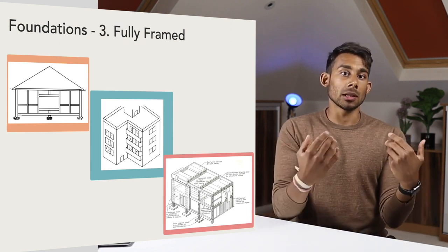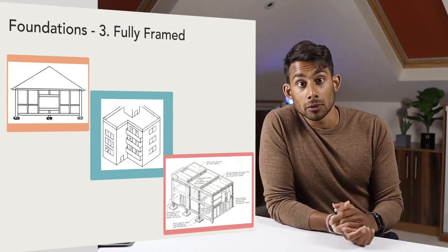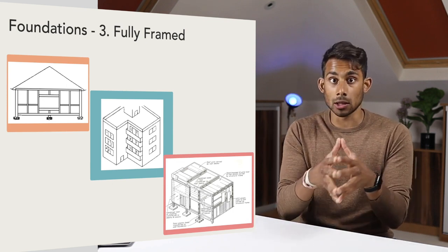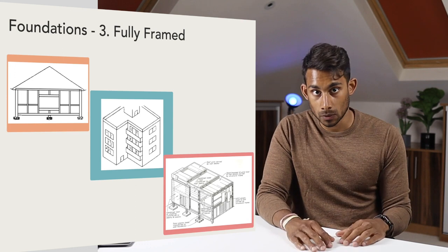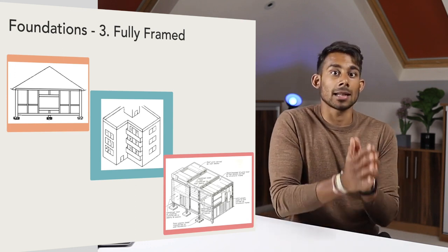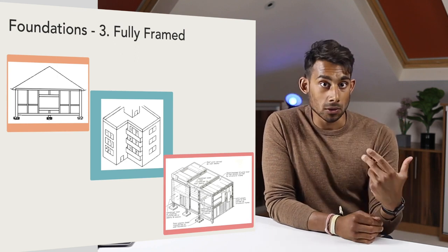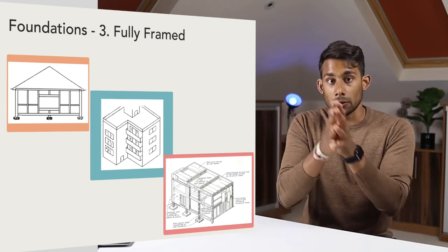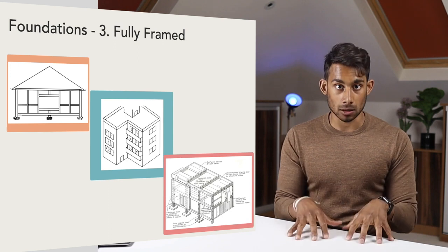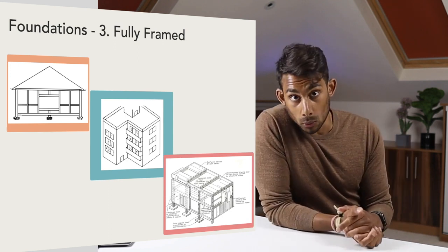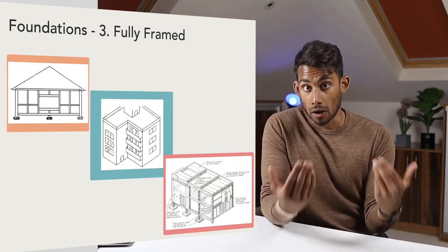Foundations are usually formed individually and may consist of comparatively small blocks of solid concrete, large reinforced concrete, or steel joists encased in concrete. The frame is formed by fixing the stanchions to their concrete bases and fixing between them, at suitable levels, steel beams which will support the floors and transmit the load to the stanchions. These stanchions or beams may be encased in concrete or brickwork to protect the steel in case of a fire.